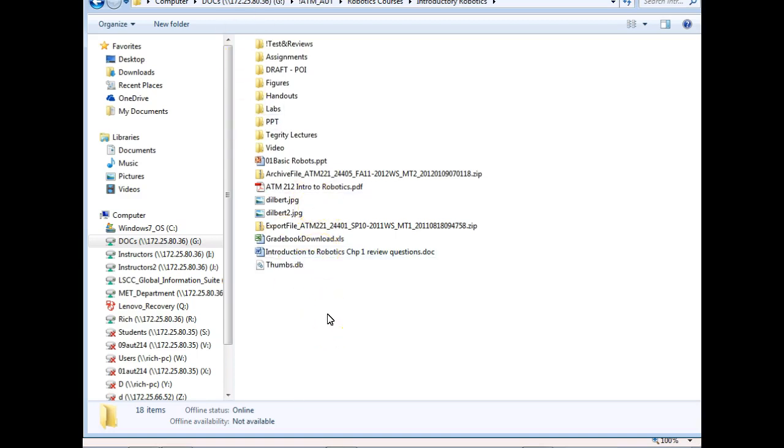So pneumatics is cheaper. Pneumatics is safer. And why is it cheaper? Because in hydraulics we have to use a lot of metal tubing because of the pressures, or reinforced piping, rubber piping, and that's very expensive.